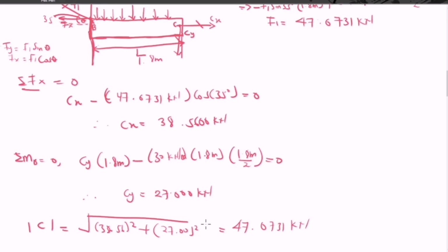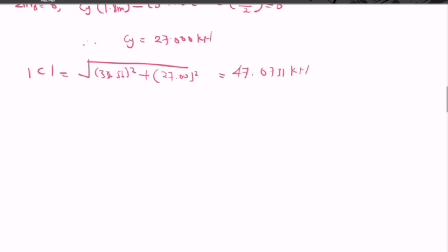So as far as we found the reaction forces, then we move on to the question. With question number 1, we are asked to find the shear stress in both pin A and pin C. So for us to find the shear stress in pin A, we know that both pins have a diameter of 25 millimeters, right?